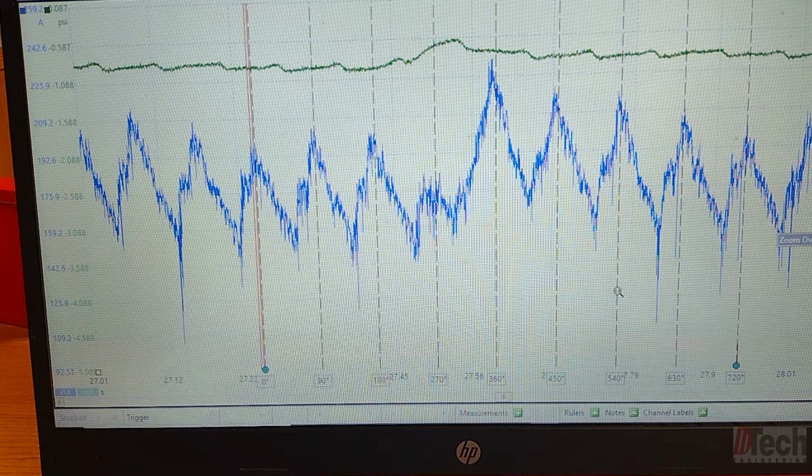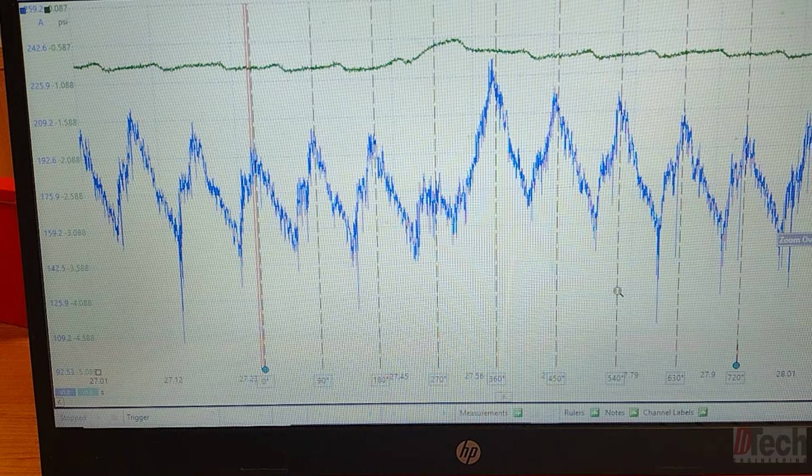As far as for me, I can try to break down a little bit of the waveforms and maybe do a little bit more fine-tuned detail testing, but again, in reality, this vehicle is quickly diagnosed with a relative compression, and it helps to have the intake trace because you can accurately tell, based on the two anomalies again, that we have a mechanical issue. Based off of having the intake, I would say, and we can break it down in detail, that we are having an intake valve issue on cylinder 8, and it's bleeding off into the intake manifold.